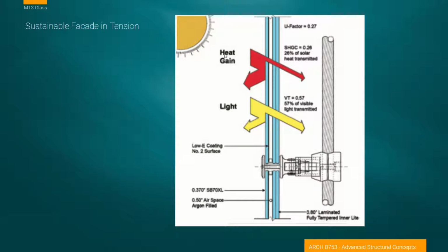In this case, we're always talking about light transmission, visible light transmission, and the solar heat gain coefficient, and how much heat can be blocked by the glass. Typically, when we think about passive solar, we really want to get as much heat through the glass in order to warm spaces. But by and large, office buildings with heavily glazed surfaces tend to pick up much more solar energy than they can deal with. So the predominance of the methodologies behind their creation and orientation is really to reduce solar heat gain, to keep from overheating our surfaces, our interiors, and needing them to be air conditioned.